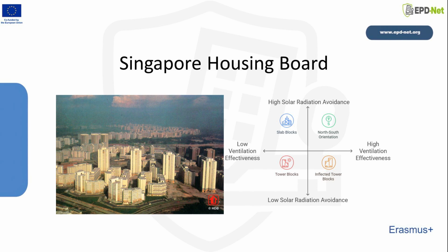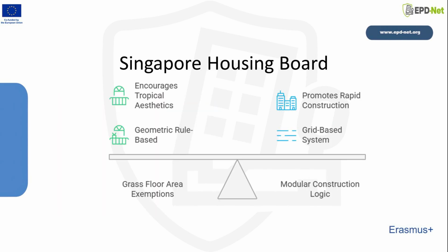Tower blocks. Developed for larger 5-room units, these layouts were highly inflected to increase vertical surface area. This design was necessary because of the requirement that all rooms, including bathrooms and kitchens, have natural ventilation, which would be difficult to achieve with smaller units in a tower configuration due to the ratio of circulation to net floor area. The parametric logic is applied to Singaporean housing.